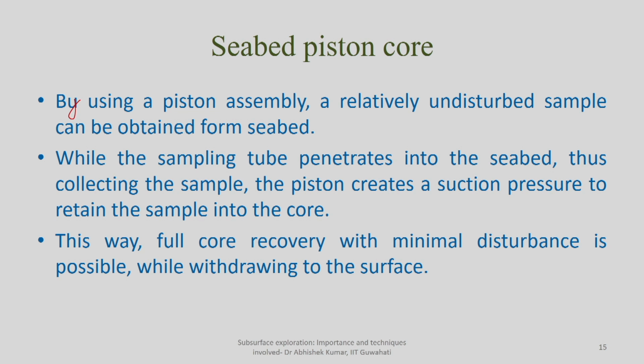Most of the time, whether it is grab box or vibro core or something else, you are imparting some kind of disturbance into the soil so that first of all it will penetrate, and second, while bringing it onto the surface, you are providing some kind of cutting shoe or maybe steel plate, which is also inducing some kind of disturbance into the collected sample.